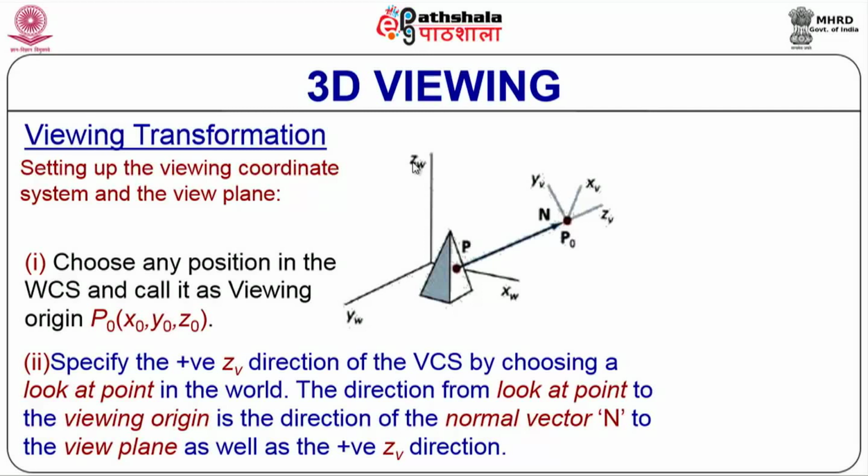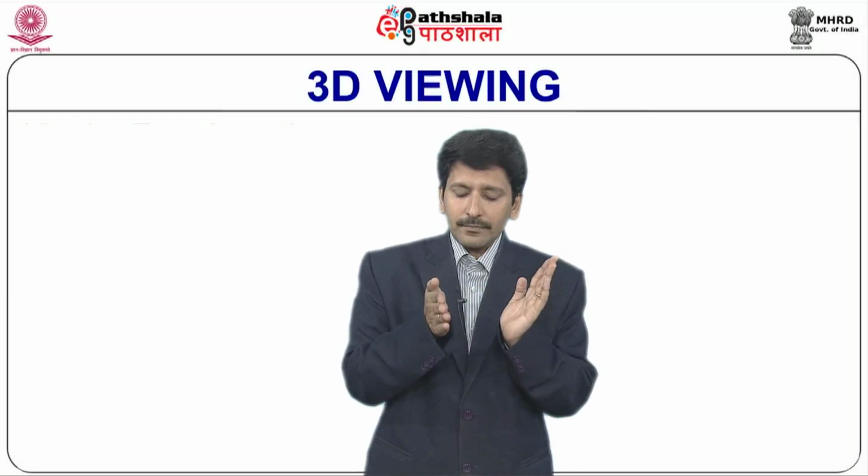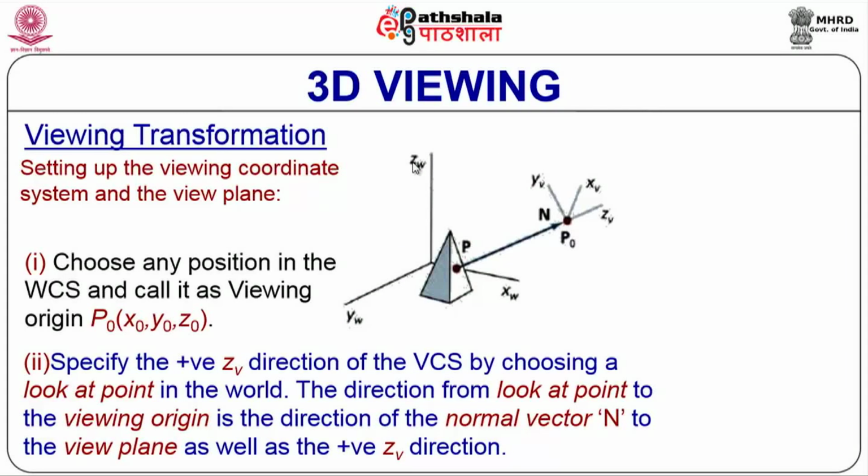So what we do is, we take a projection of this y direction onto the plane which is perpendicular to the z direction. Let me repeat, because y should be exactly perpendicular to the x direction, and also should be within the plane containing x and y, which is the plane perpendicular to the z direction. So we will be projecting this direction onto the plane that is exactly perpendicular to the z direction. When we project it, we get an assumed, rough y direction, an approximate y direction. Still it is not correct.